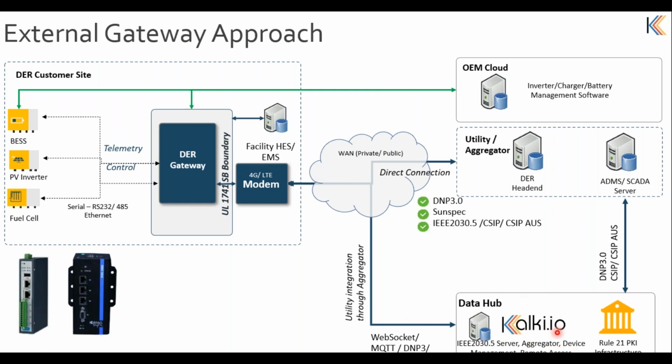So Kalki can also act as an aggregator, where you can aggregate data from multiple sites and provide either a single 2030.5 link to the SCADA, to the utility backend system, or it can also aggregate and provide REST APIs or other IT integration options like Kafka or MQTT integration to the external applications like market or ISOs.